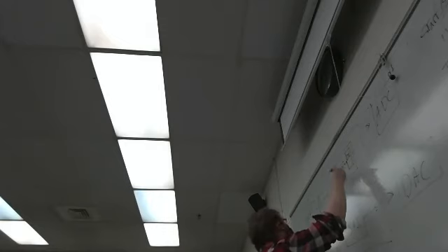Yes, and your ADC is going to be generating data at a rate of about 78K. So just like the review question we just did with the FIFO, you're going to need to put a FIFO in between here and there. And you won't write the FIFO, you'll just use the IP core FIFO.